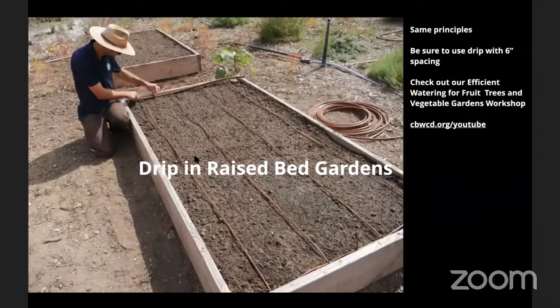Personally, when I plant seeds to get the seeds up, I always water by hand. But then as soon as they get going, I just convert to running the drip. Standard landscape drip irrigation, the closest you can buy that is 1 foot apart between the emitters, which for me, I believe is too far in between vegetables, especially if you're growing all sorts of different vegetables at different times of the year. So I highly, highly recommend that you make sure that you use drip with a 6-inch spacing.